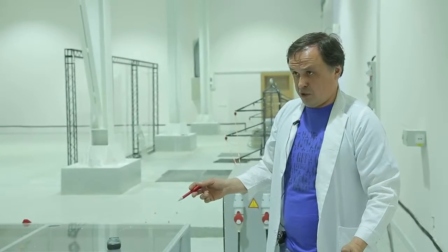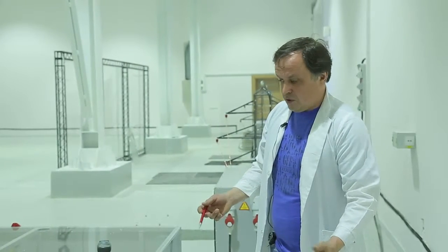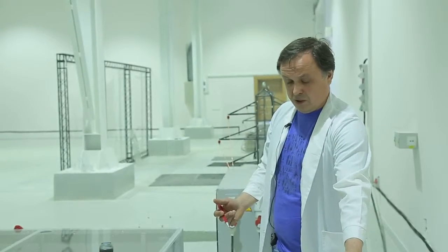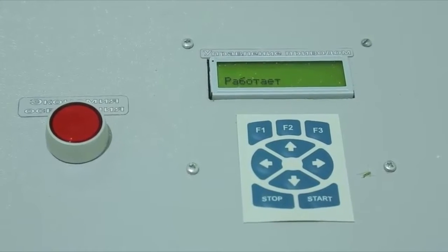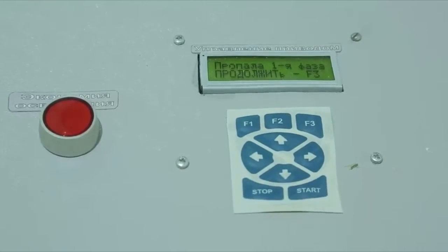As we see, the motor is gradually started. The device transmits information about motor status via GSM channel. Moreover, if the operator does not make a decision within the specified time, it slowly turns the motor off to avoid hydro-hammering. Display will initiate open phase.